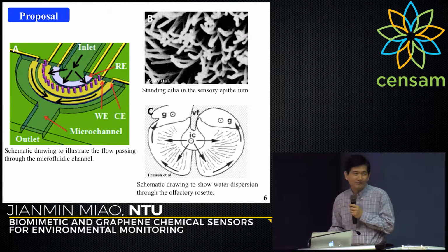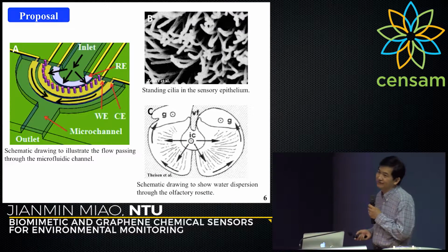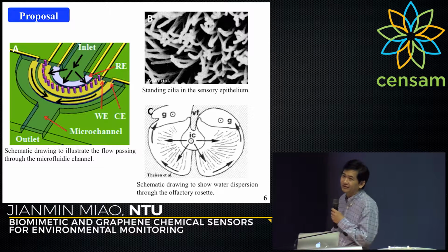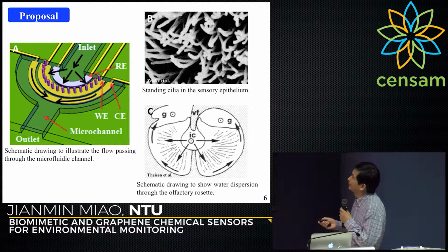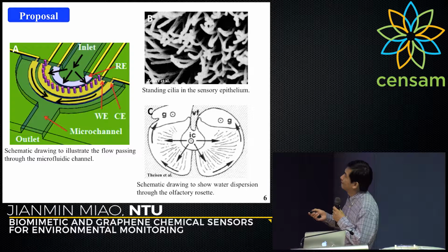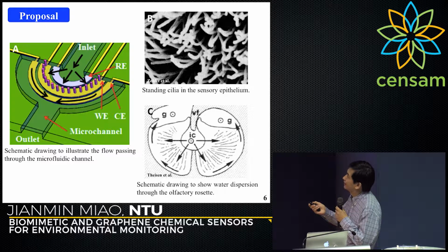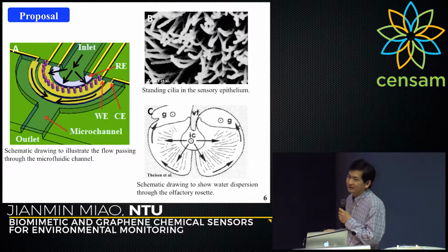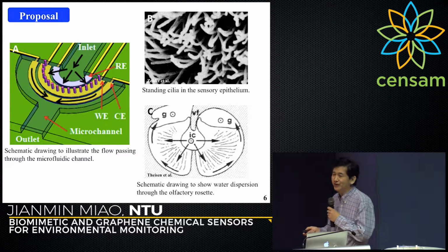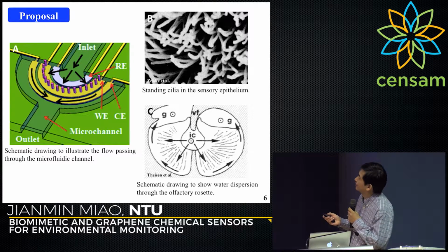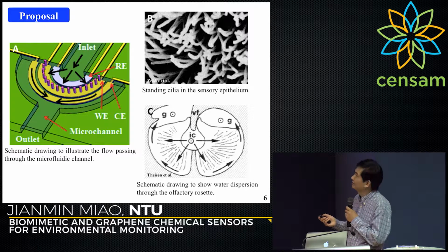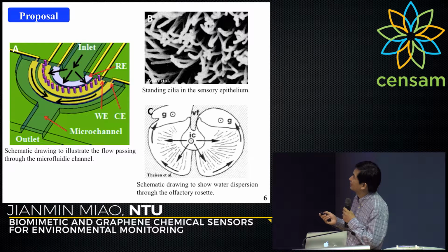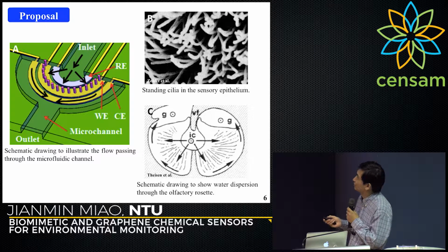Based on that concept, we designed this MEMS device. We have the microchannel, and this inlet comes into the detection area with three electrodes. One is the working electrode, another one is the counter electrode, and this is the reference electrode.